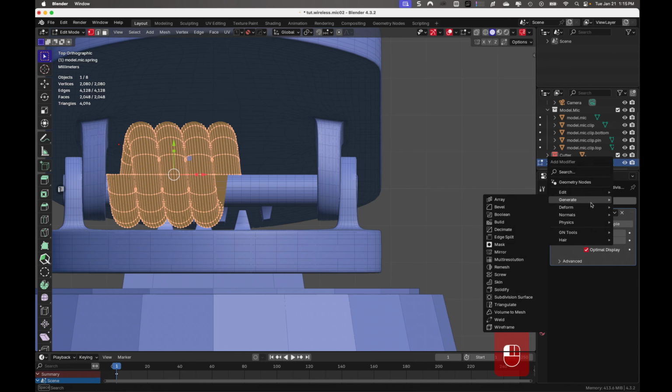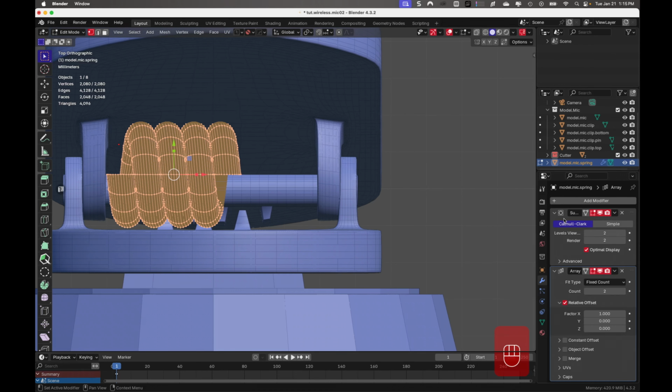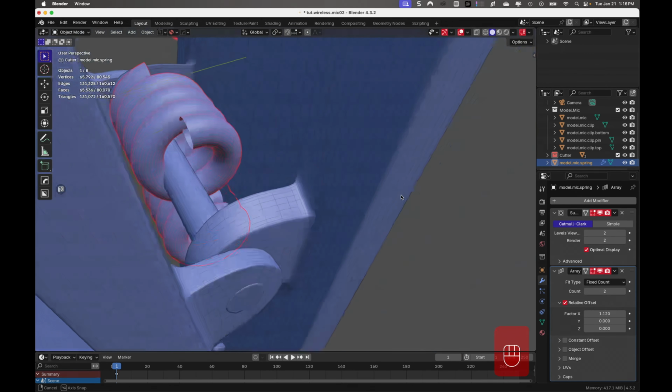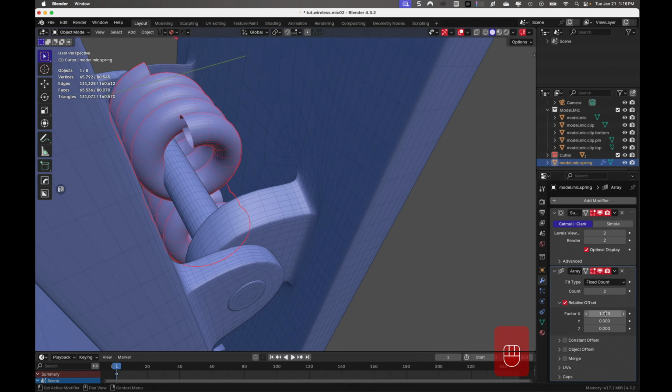So it's not long enough, it's not wide enough, and I don't want to stretch it because it won't look good. So I'm going to create an array modifier. That's going to keep the same perspective it has now, but it's just going to create another duplicate of it. And let me check. I think I might be on the wrong axis. Hold on. Yep, that's what it is. Let me go ahead and fix this. Get it on the right axis.